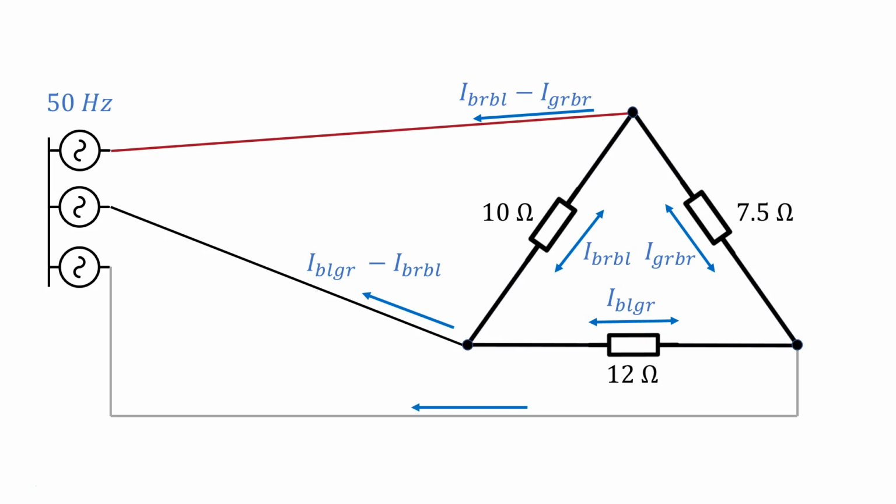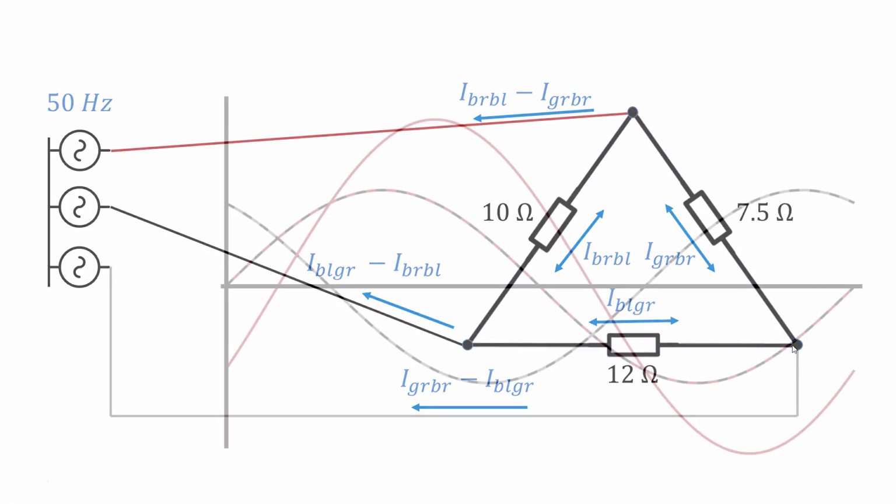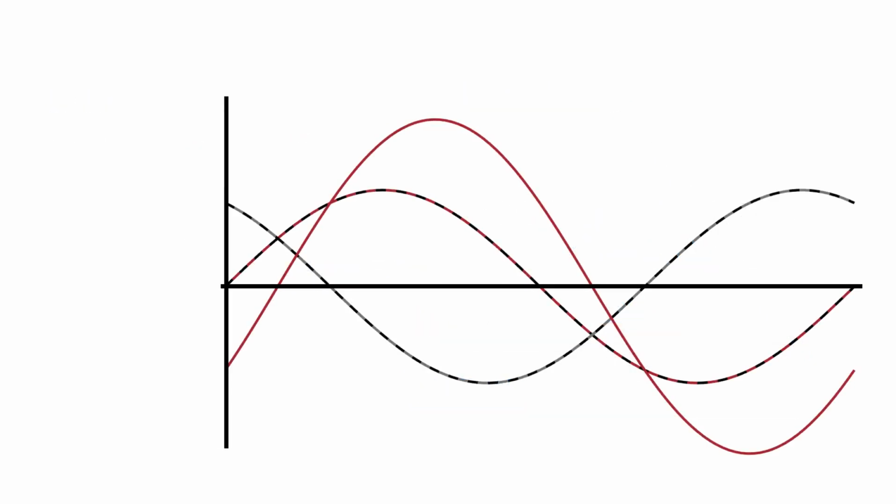And if you're already a couple of steps ahead, you'll have figured out that the line 3 current is the difference between the phase 3 current and phase 2 current, as they are both reaching this node here. So this is just an illustration to show you, if we take just a purely resistive circuit and a balanced circuit as well. So the impedance is the same, so the currents here are exactly the same.